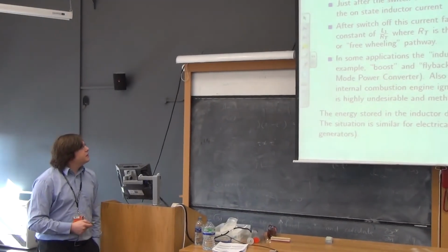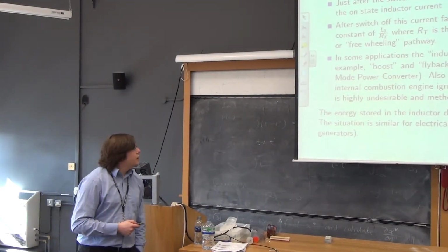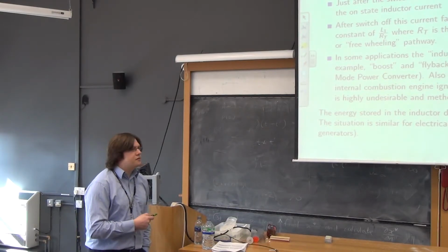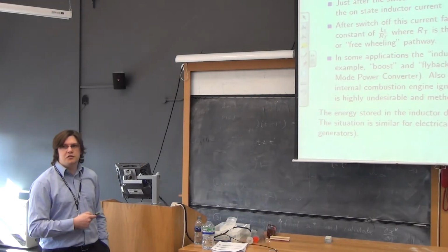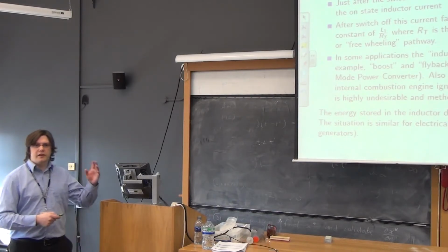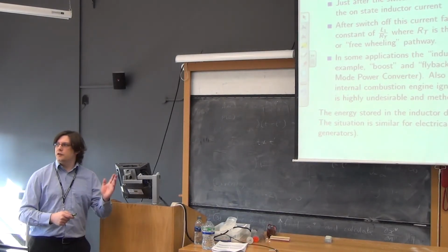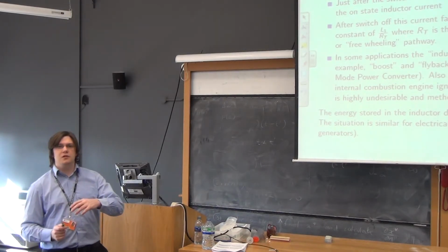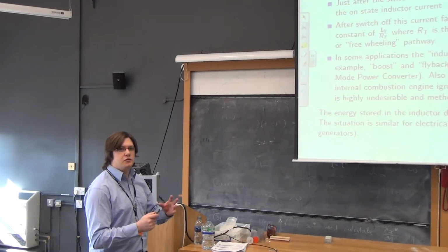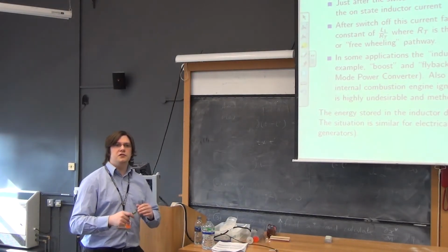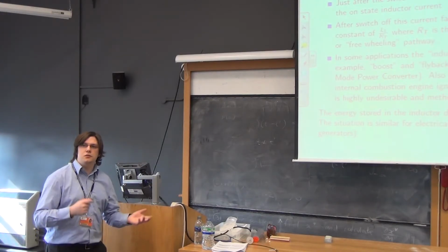So in some applications, this inductive kick is desirable. Certain types of switching converter will make use of this property of getting a current flowing in an inductor and suddenly opening the circuit and then catching that voltage somewhere else, or the charge which goes along with it, in another circuit, and using it to change one DC voltage into another.